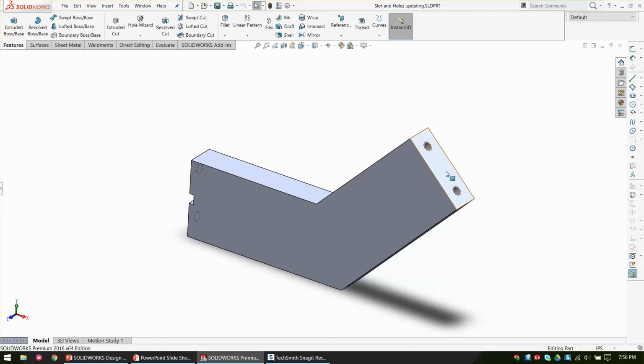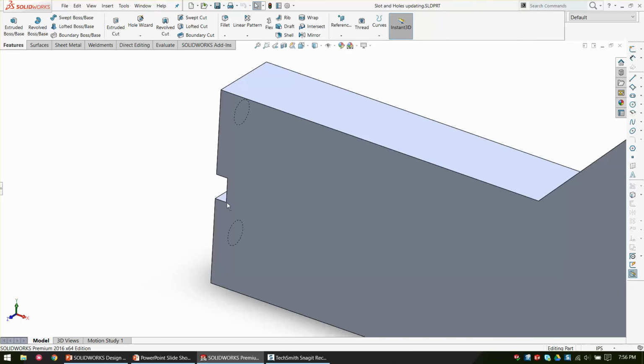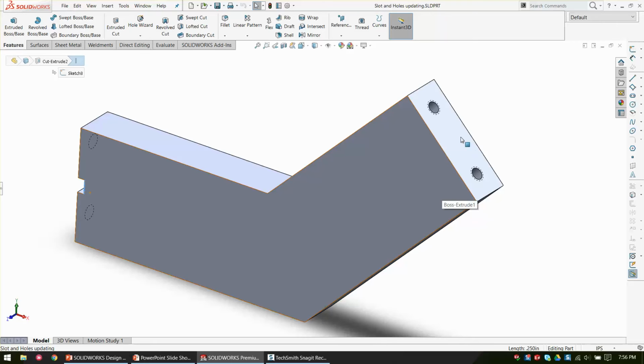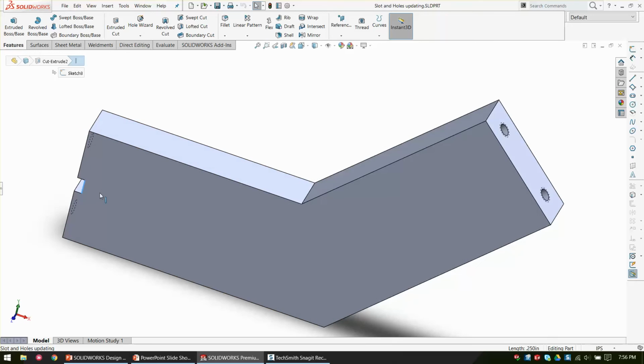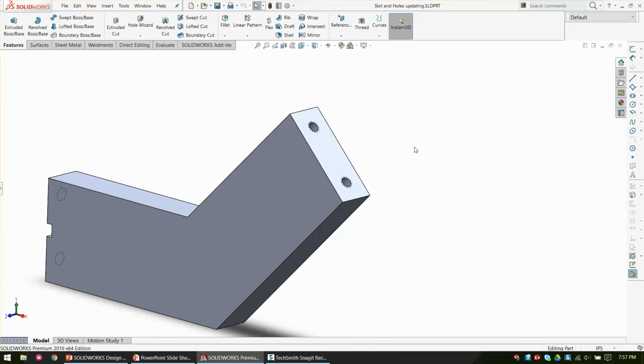It's going to be in the middle. Keyways are always square, so we get half of it, so this is an 1/8 inch by 1/4 inch. So I need an 1/8 inch by 1/4 inch keyway here. How would we go about doing that? You can't mirror it because it's not exactly parallel, it's up on an angle. So we're going to have to recreate it in a sketch in some capacity.